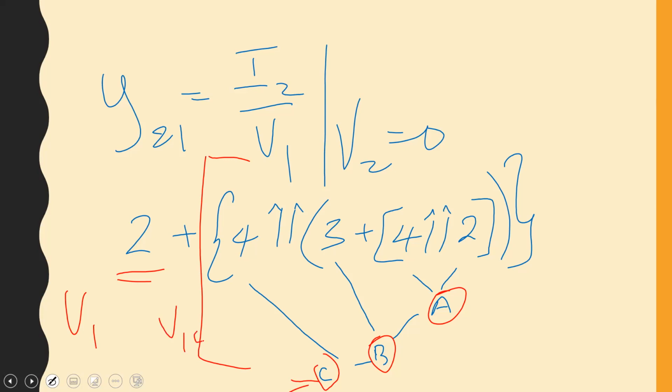Whatever is across V1C is across the 4, so it's also across everything here. So it means therefore that V1C would be across the 3 and everything beyond that. You then, because you have another plus here, voltage division again. So you are going to now have V1, I'm calling it CA. So V1 CA would be across these two resistors.